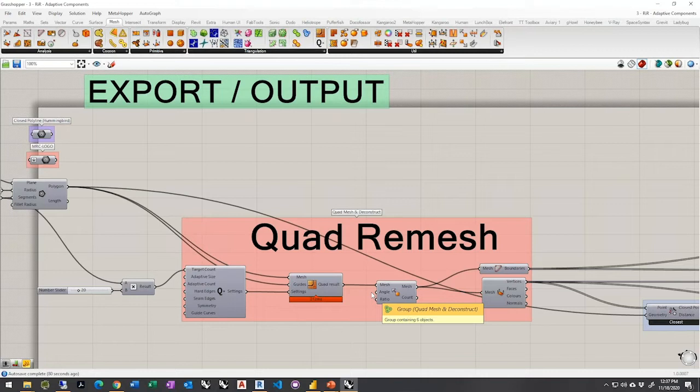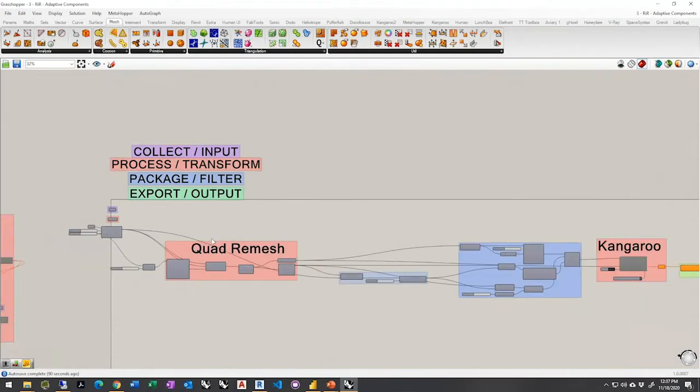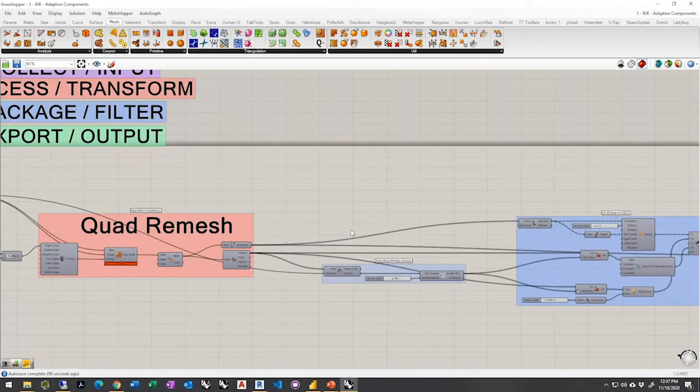I will feed those 4 points into an adaptive component that has 4 adaptive points. And this can be applied to adaptive components of however many adaptive points. It just requires that they match up so that you're feeding in the number that that component requires.